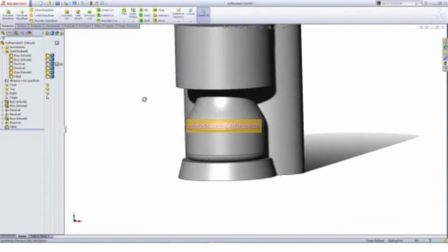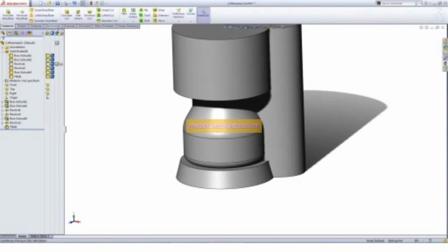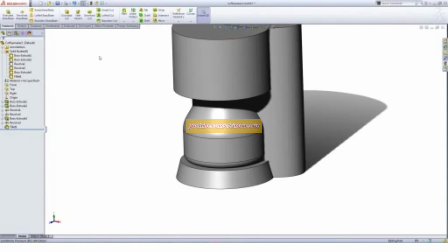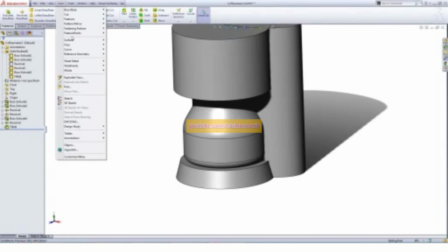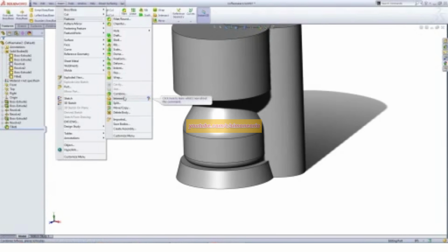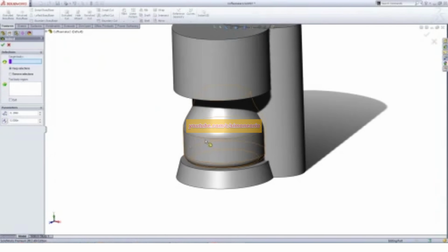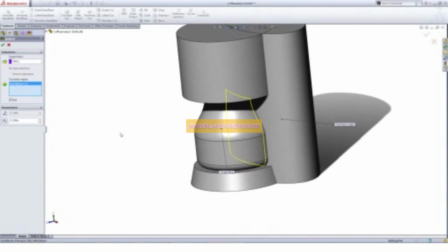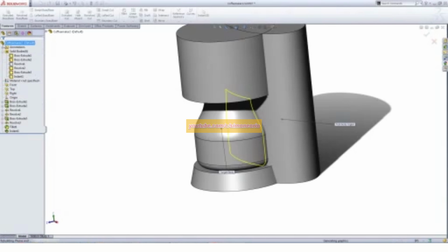All right, and now I'm going to use a really nice command in SOLIDWORKS called indent, which lets me just kind of reserve some space for a couple of different volumes that intersect each other. Go grab that command over here, and we're going to take that part and make a little bit of room for it inside this overall shape, and maybe we need to have about a 1/4 inch or so around the outside of that, 1/4 inch of space.